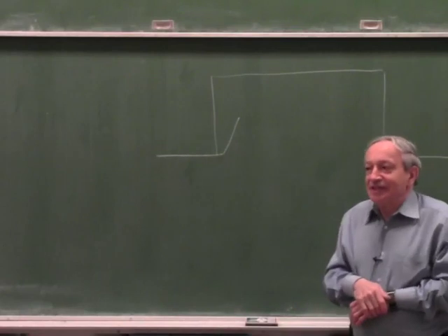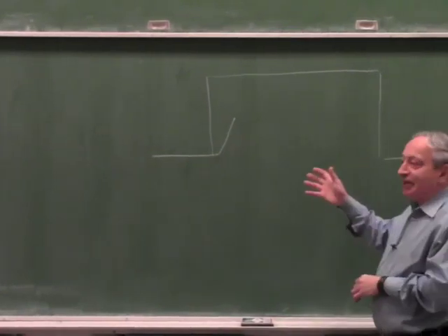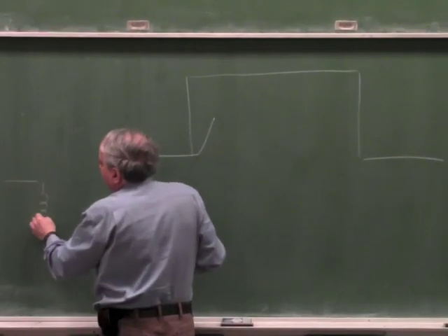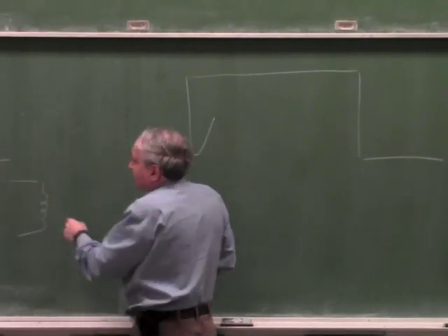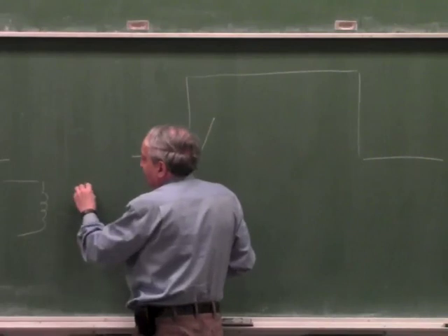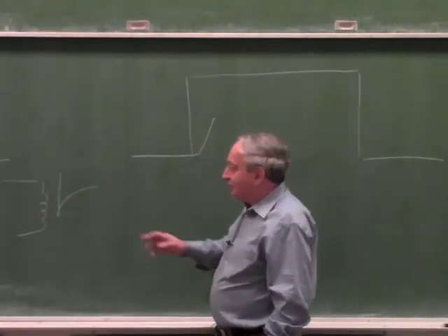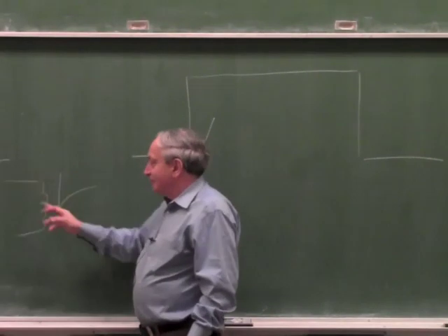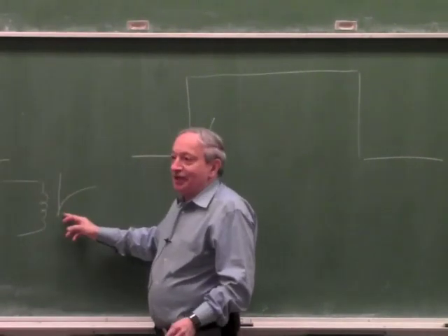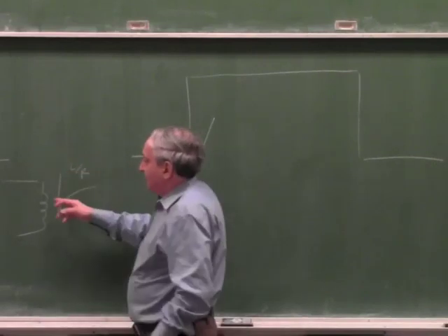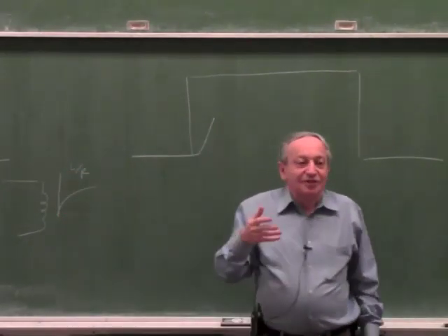The first reason is electrical. If you're talking about an electromechanical actuator, when you give it the command, say the current jumps, nothing happens because of something you all know, there's a time constant, okay? So just because you gave it a command, even before inertia, it takes a time constant, say L over R, until the current really is strong enough to do a lot.